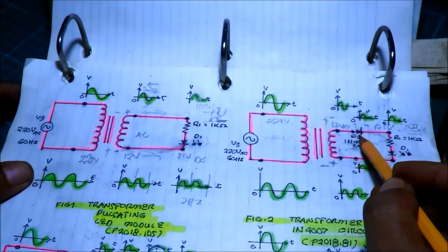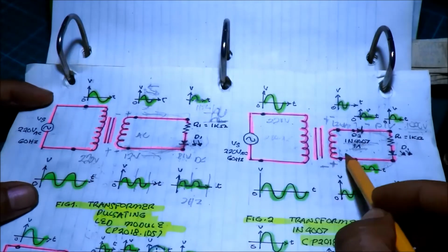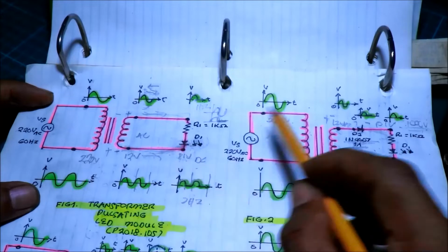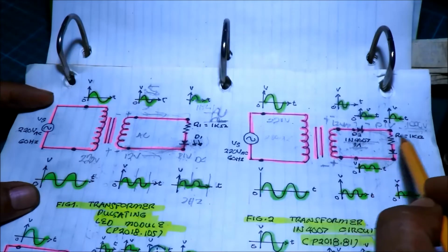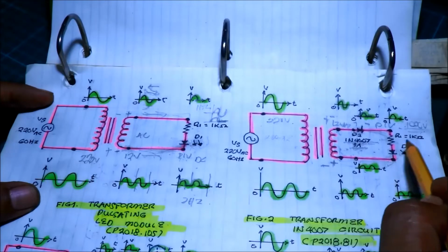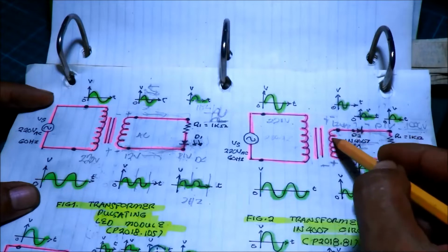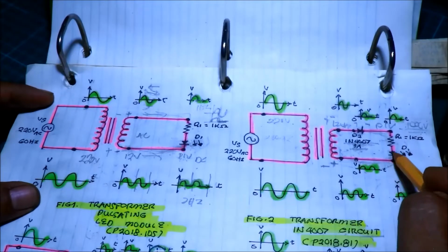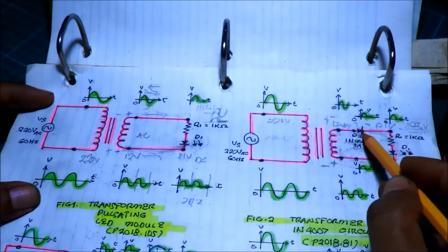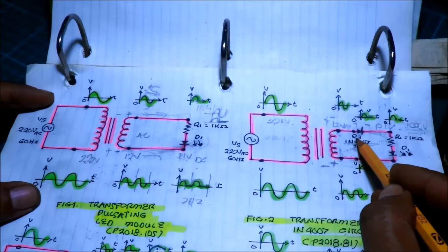That is the use of a diode in the circuit. And this is the modification of this. Just connect a diode in series with the load, with the LED, and it will protect the LED from burning due to the reversal or the reverse bias condition of the LED. It will not break or burn out due to the high PIV rating of the diode.